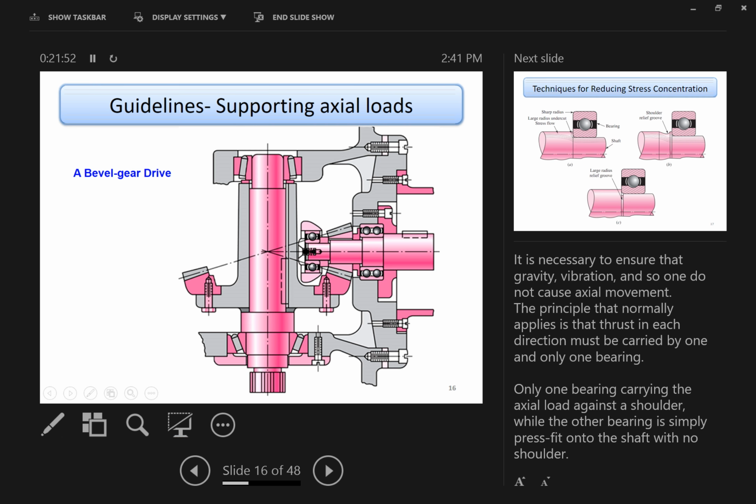But the other side of the bearing, look at that thrust bearing here, that bearing is what we call floating. So the shaft here can expand to a certain degree because of the floating mechanism structure here. That gives you an example of how you can design your bearing to accommodate that type of consideration.